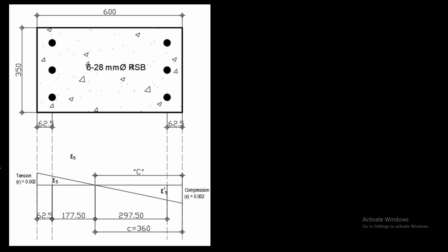So as stated, assuming this is the compression side, we have a strain of 0.003. Sorry for the erasure. For the compression side, 0.003 of the strain, and for the tension side, we have 0.002.